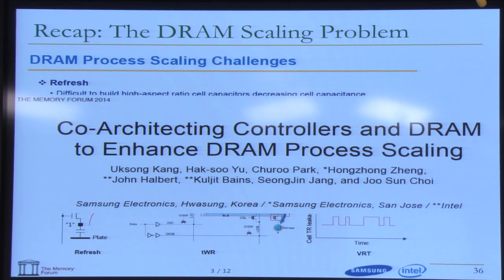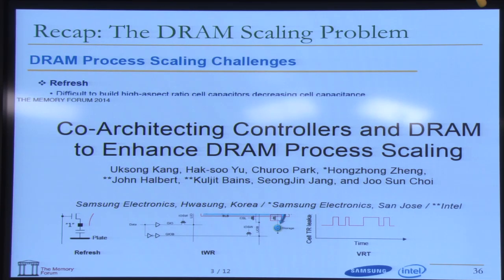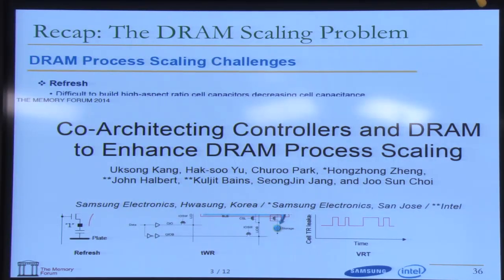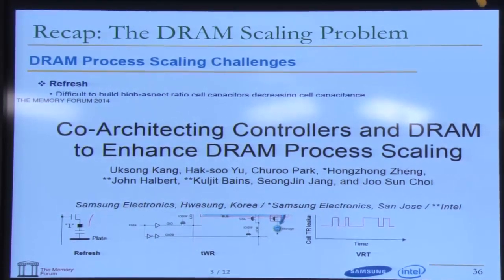But they also realize that this is a problem, and maybe you need to solve the problem by taking a look at controllers and DRAM together, somehow designing DRAM and controllers together. Does this remind you of something? Hard disks, flash memory. If you think of hard disks and flash memory, they don't come just by themselves, right? I mean, they do, I guess, but hard disks come with a controller together, right? The controller actually manages the errors. Flash memory also comes in an SSD, and the flash controller actually manages those errors.